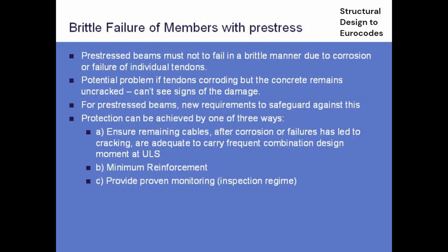And then under that same load combination, you then have to check that, having lost the tensile strength of the concrete, there is enough resistance in the remaining pre-stressing at the ultimate limit state to carry that same load combination. So it's pretty obvious, really. It's just saying to work out for a given load case how many tendons you would have to lose for it to crack, then assume that happens, and does it still stand up once it's cracked and you've lost the tensile strength. If you do that, as I say, you can almost always prove that it's fine.